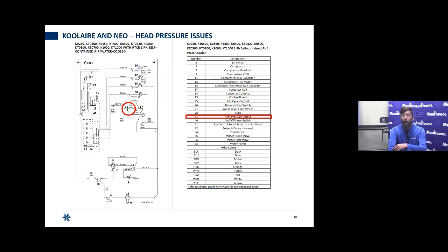If this was an old piece of equipment, S series or earlier, the high pressure switch was wired in series with L1 going to the board. So on this style machine back then, that was wire 55, and on the Cool Air, it's also wire 55. You'd lose wire 55 and all lights would turn off, nothing would be running until that switch automatically reset itself. Then it would boot back up and start back up.